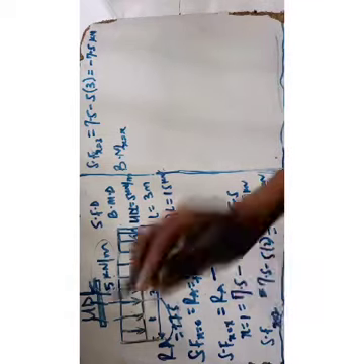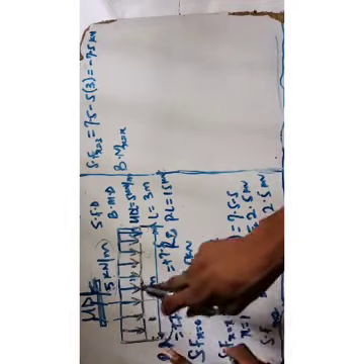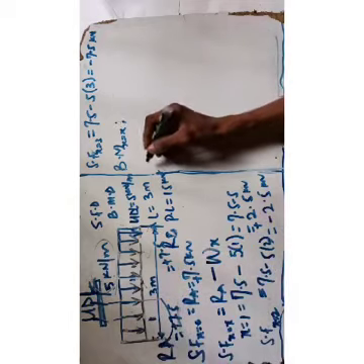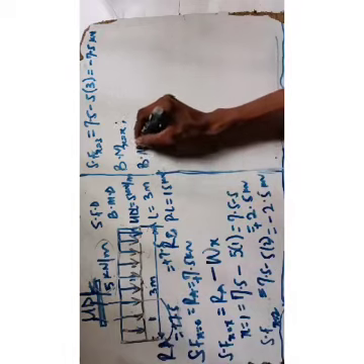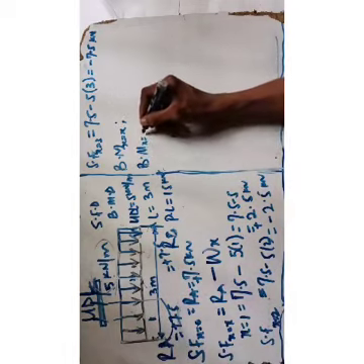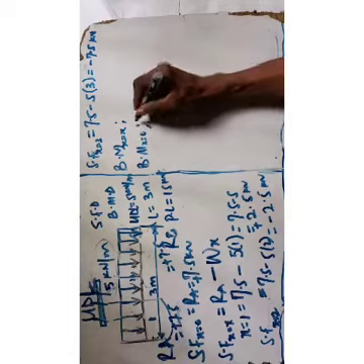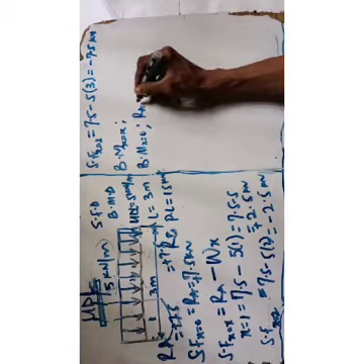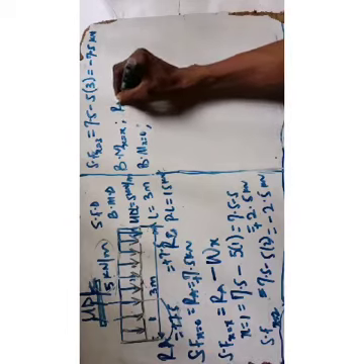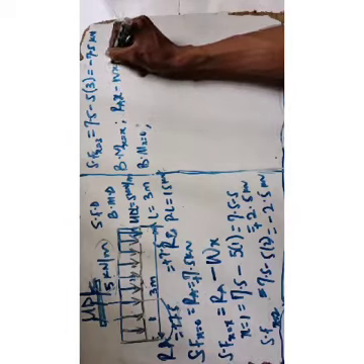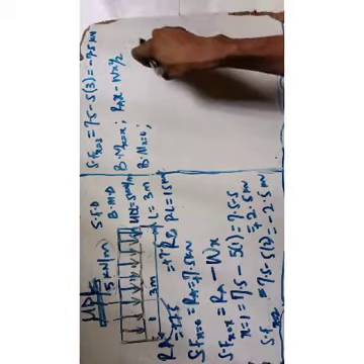this question here, if I want to take my bending moment at this point when it is RA, 0.0 here, okay, so I'm going to have it as my RA, that is bending moment when x equal to, let's say, 0. That will be bending moment when x equals 0 is always 0, because the formula you always have it as RA, that is the force, okay. So, and you know the formula states RA x minus WX square over 2, don't just cram this formula, okay, but it's advisable you also know it.